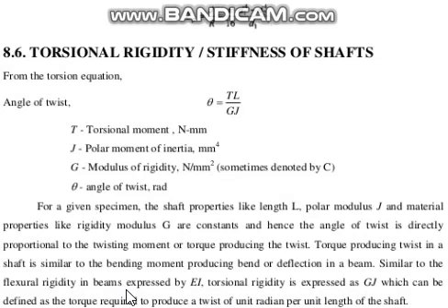So similar to the flexural rigidity in beams, EI, which is what we call the flexural rigidity of beams subjected to bending, where E is the Young's modulus and I is the moment of inertia. Similarly, for torsional rigidity, E is replaced by G and I is replaced by J. GJ is called the torsional rigidity.